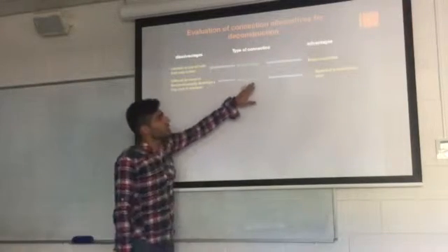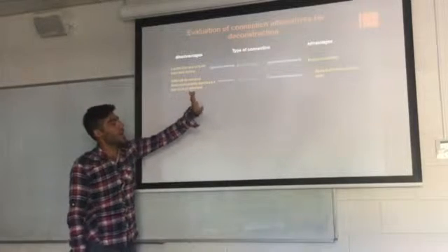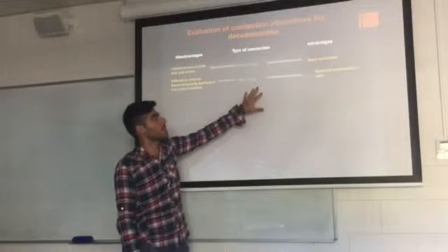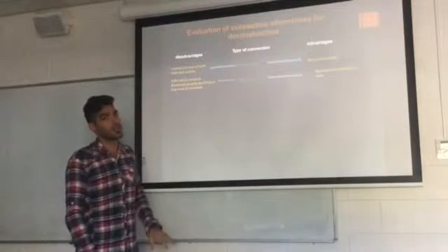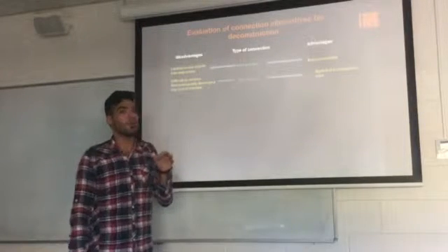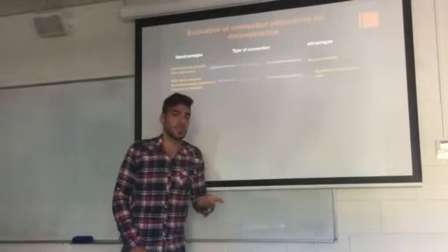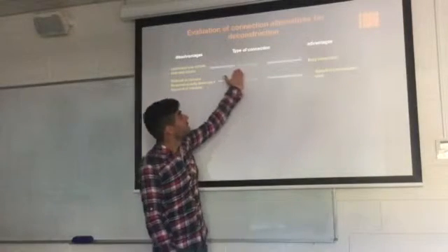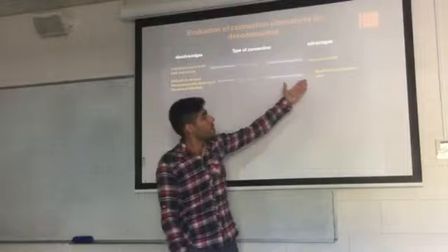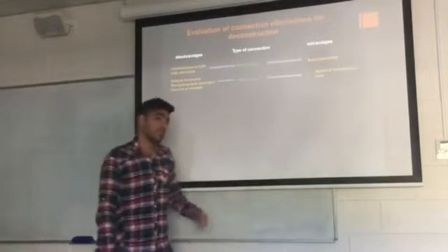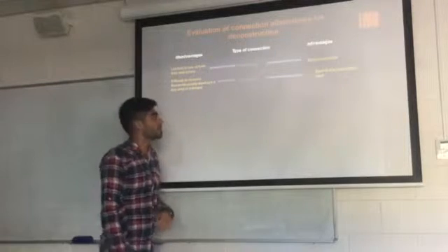Okay, next slide is about types of connection between elements, between components. Screw fixing and nail fixing have advantages and disadvantages, and I present them for comparison of all our connections, because it's really important to choose the best connection for the whole building, because we need reconstruction, we need beneficial reconstructions. Screw fixing is easily removable, and nail fixing is fast to connect.